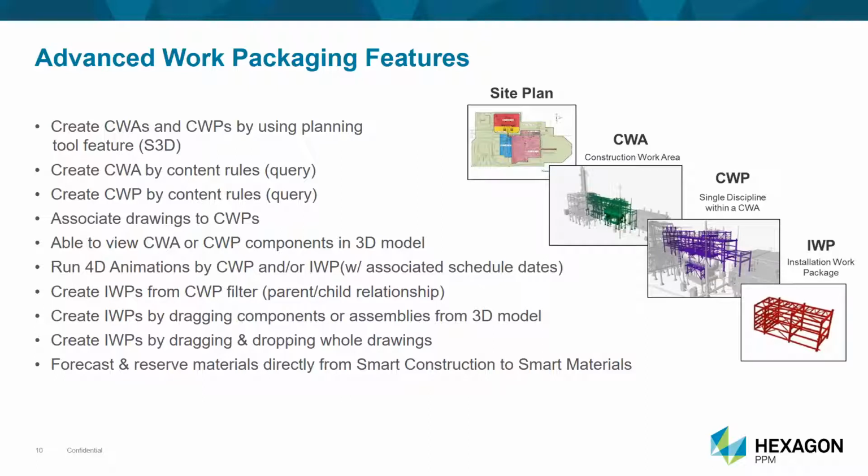We can do that. The beauty of that is if it's during early planning, you have the capability as the model changes, you can refresh those queries and it fills in or adds to the CWAs and CWPs as your design matures. So you don't have to basically do a standalone CWP, create it, and then once you get a refresh of your model, basically have to manually go back through and reselect the new items that have come into the model. You can simply refresh your queries and they will automatically bring those into your CWAs and CWPs.